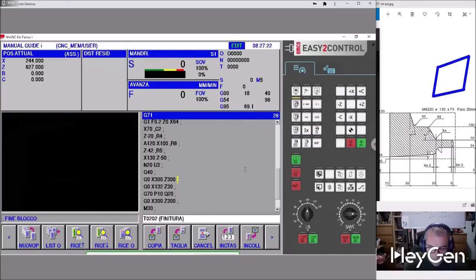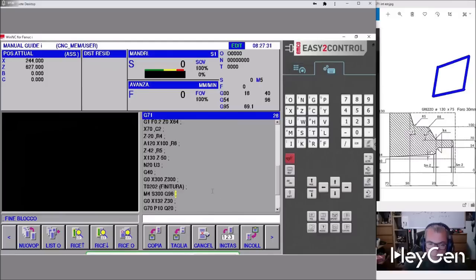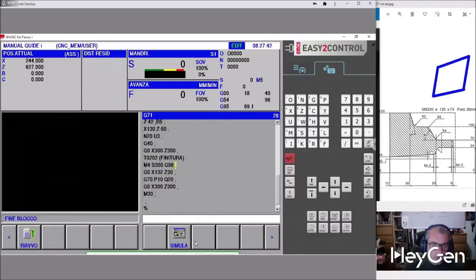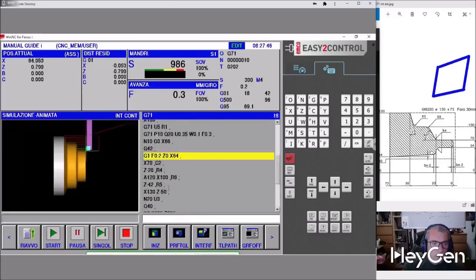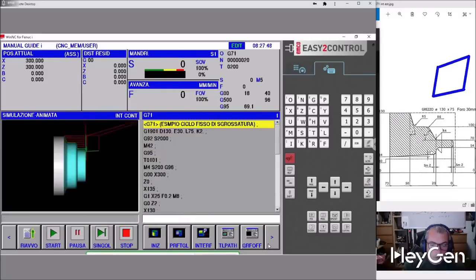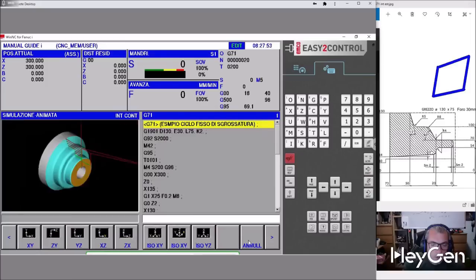Now, work inside. First step, create tool, take T3, tool correction, enter geometry T3. When you call up a program, always include the data related to spindle rotation and any other relevant parameters, so that if you need to search for the block, you already have the rotation data and can quickly access it with ease. You see, this way you can clearly distinguish what's happening in the process.